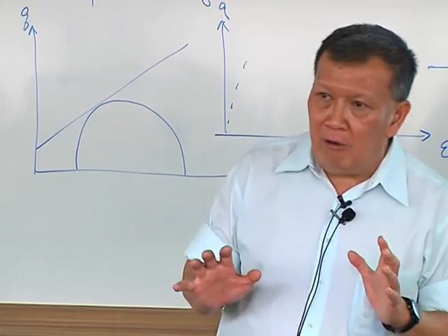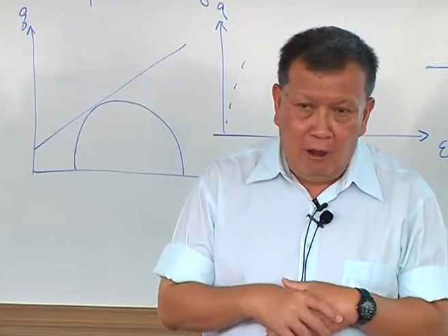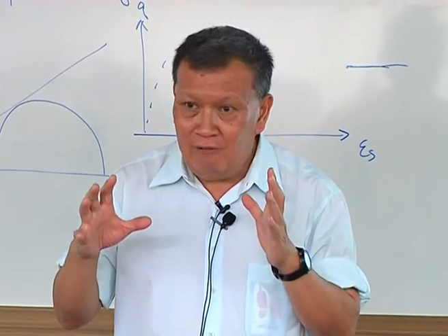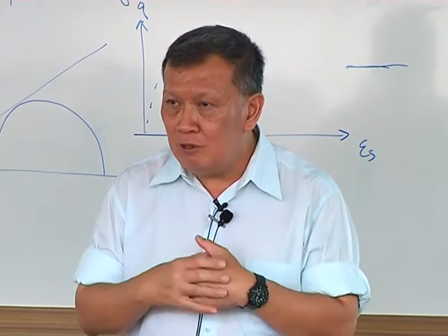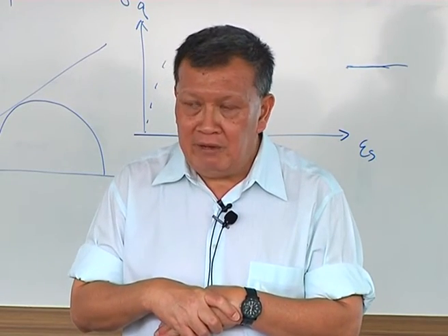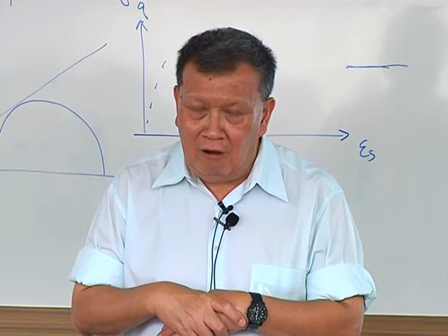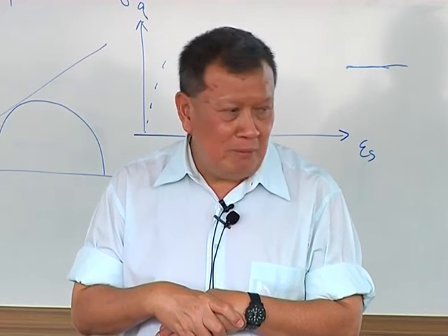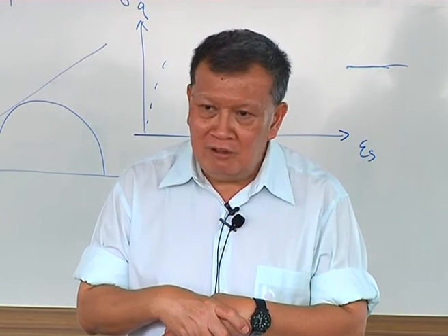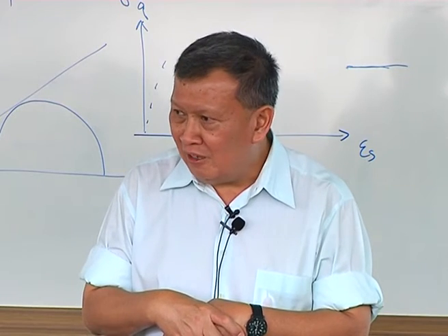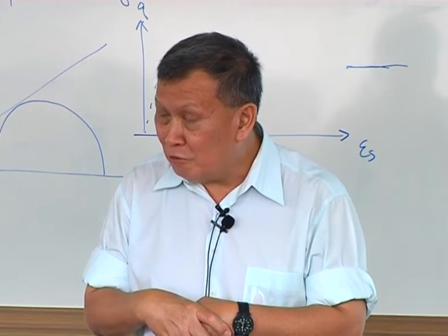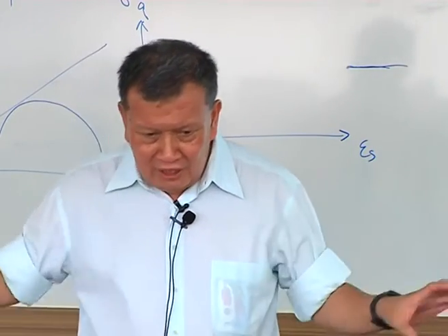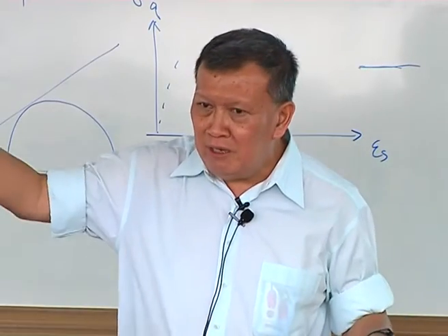Now, I'm not sure it is arguable as to how important this is. Obviously, the Plaxis people think this is important to get the K0 value right for the soil. I'm not saying that it's not correct. This is correct. But my question is, how well do you really know the K0 value of a soil? If you read Schmertmann in America, he will tell you K0 is one of the most unknown parameters in the real soil. Because on level ground, everything uniform, horizontally layered, your K0 is still fine. If you have a sloping ground, how do you determine K0?